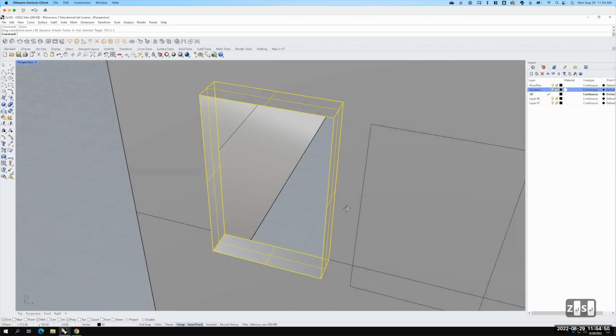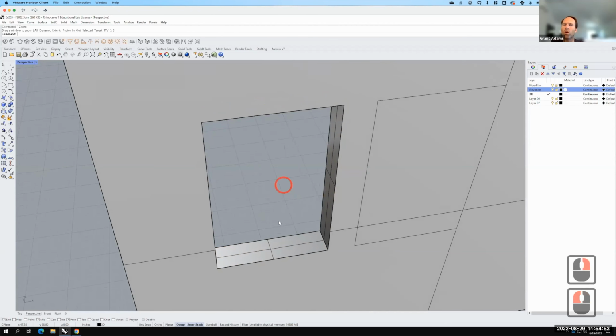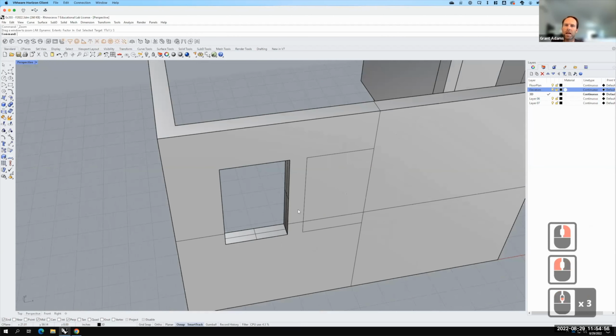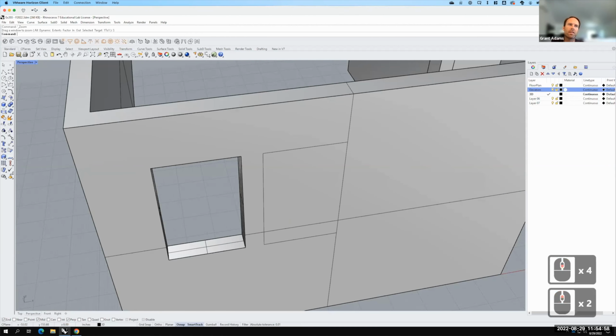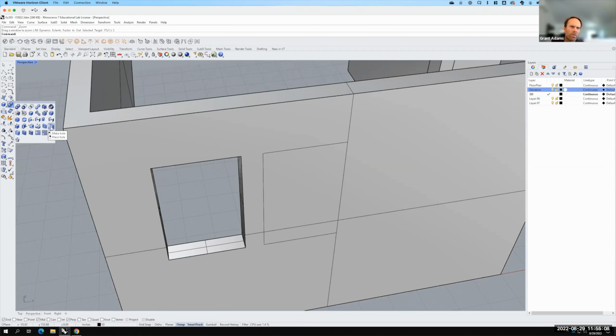Like that. So it filled it in. So there's nothing wrong with using that as a strategy, but there are other solutions as well. First one is hidden underneath the Boolean controls here. And instead of a Boolean union, we're actually going to use a command called make hole. That's a round hole. Where is it? There it is, make hole.